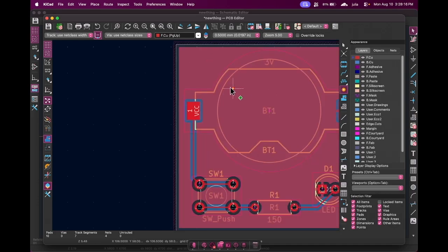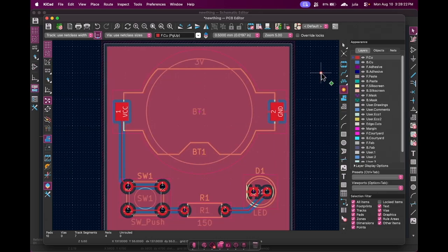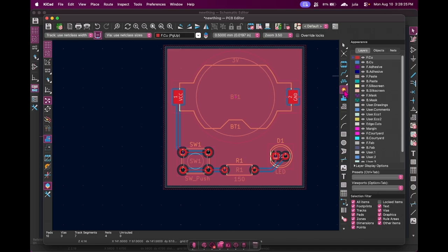Anyways, so you have your ground plane and it's beautiful. Now you're going to click the vias button and place them around your ground plane. These are called standing vias. Standing vias are vias that aren't attached to a trace, they're just there. They help with the structure of your board and help the ground planes be connected. You can place them literally anywhere.